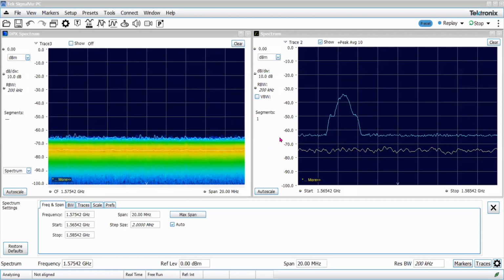Now, if you connect a GPS antenna to your spectrum analyzer, you don't see it like this, because I showed you that the signal coming to the antenna is minus 130 dBm. And that is well below the thermal noise of minus 110. So it's hidden inside the noise. So you can't see any GPS signal using the spectrum analyzer.